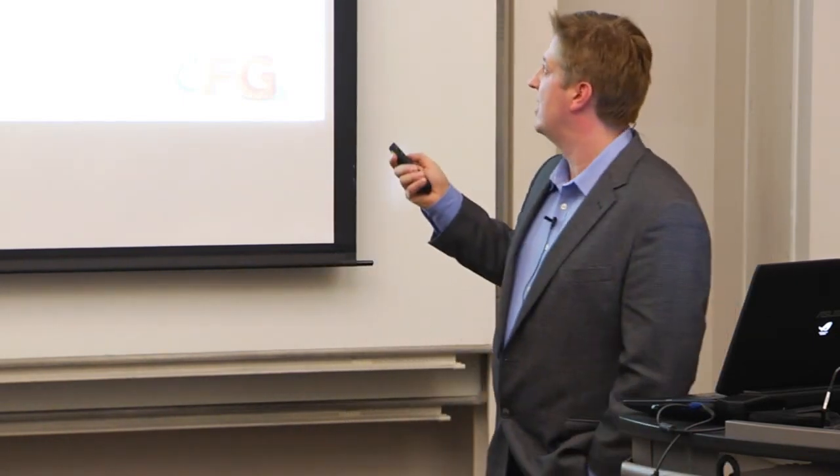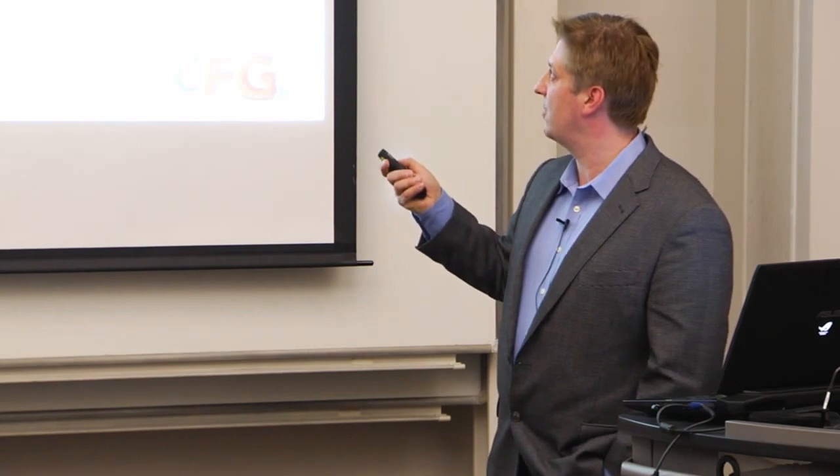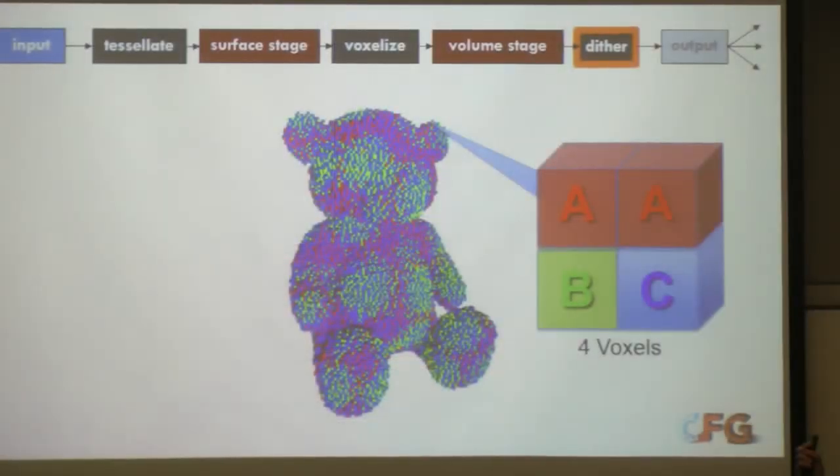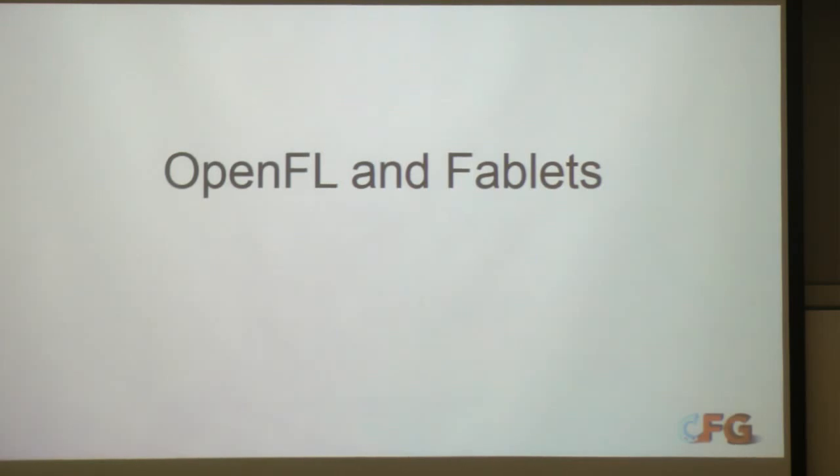And so in this case, for this particular voxel, we are going to assign some material A, and then in the neighborhood, we are going to assign specific materials such that the overall error in that neighborhood is distributed. So in this case, we would use something like the Floyd-Steinberg error diffusion algorithm. And finally, we have the output.